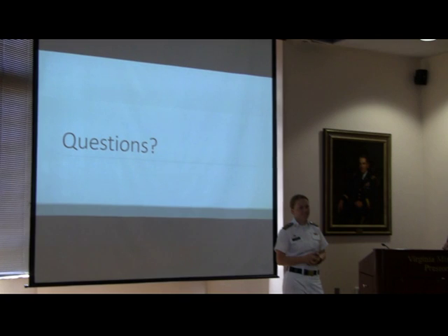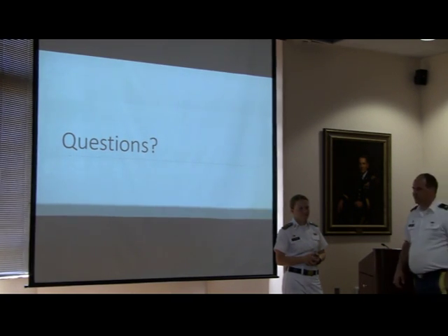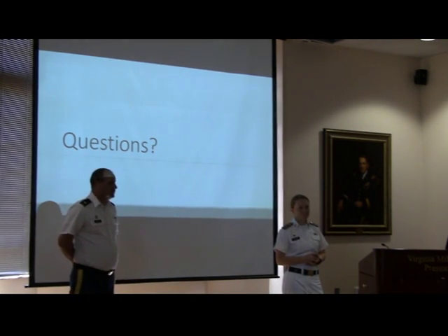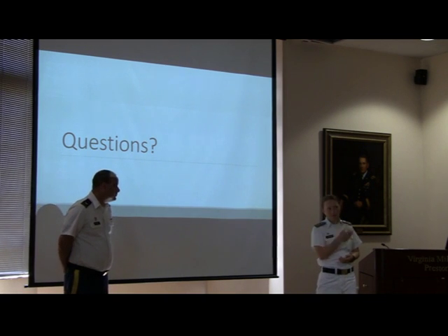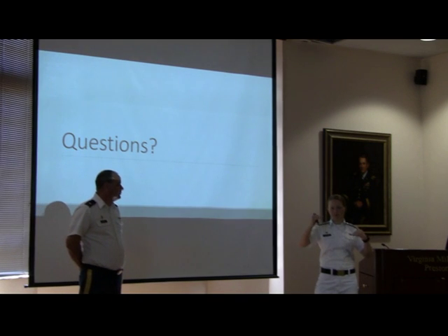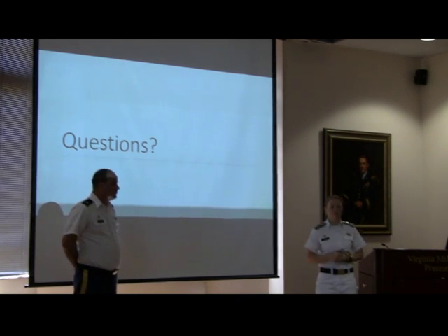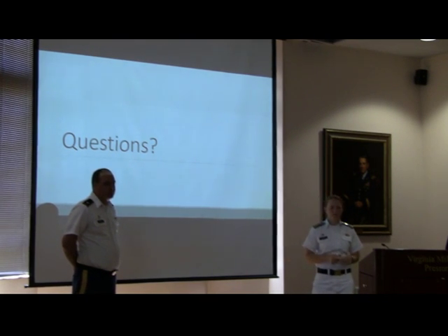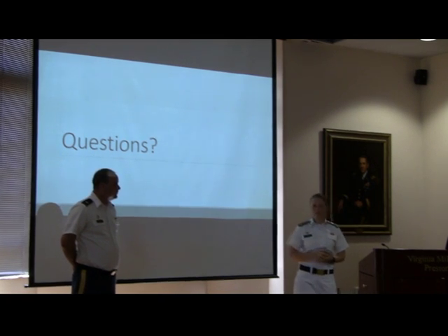It's very small. Have you thought about just doing it as an experiment, clamping both ends and driving the piezo? Then you could model it as a standing wave and have an idea of where you would expect nodes and antinodes to be, and then run your experiment to see if you can detect those nodes and antinodes. Yeah, and that was kind of the idea here, because even with it being cantilever, it still acts as if the free end is secure. But in that case, you would have an idea of where the nodes and antinodes should be. Yeah, that'd probably be a good way to refine models for sure.